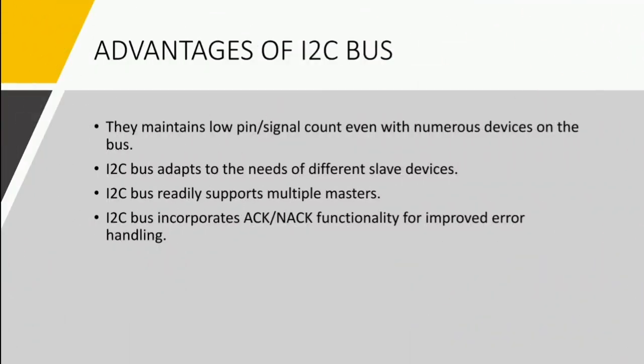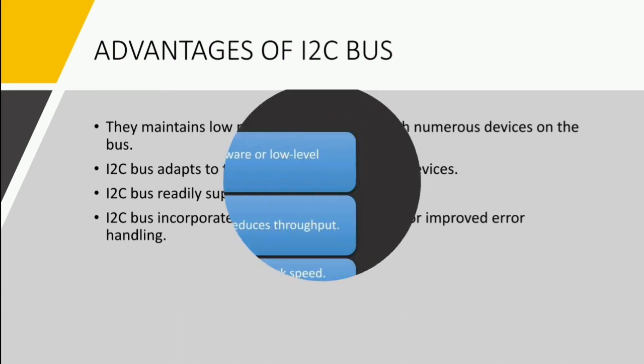In advantages of I2C bus, I2C bus maintains low pin or signal count even with numerous devices on the bus. I2C bus adapts to the needs of different slave devices and readily supports multiple masters. I2C bus also incorporates ACK or NACK functionality for improved error handling.